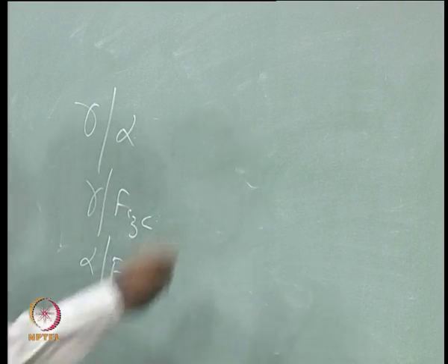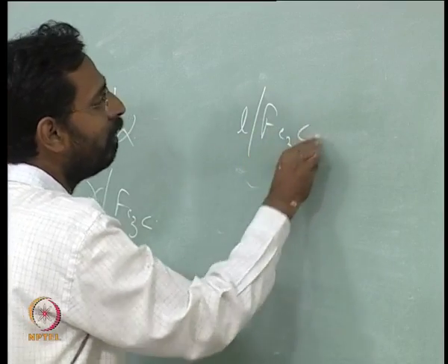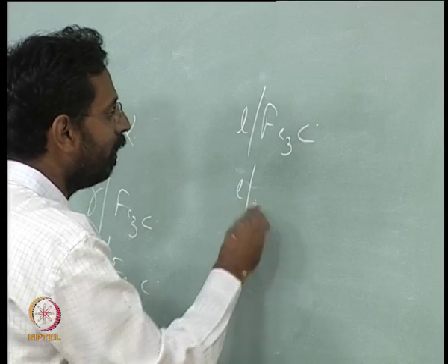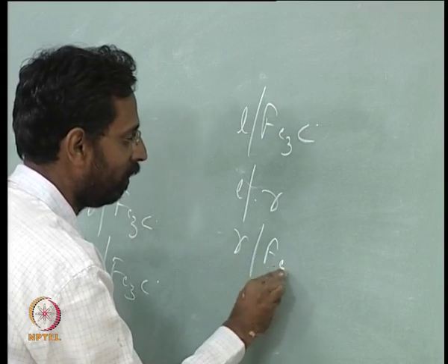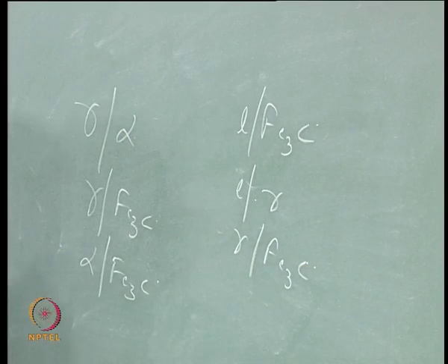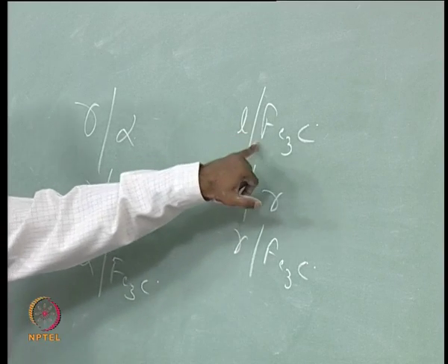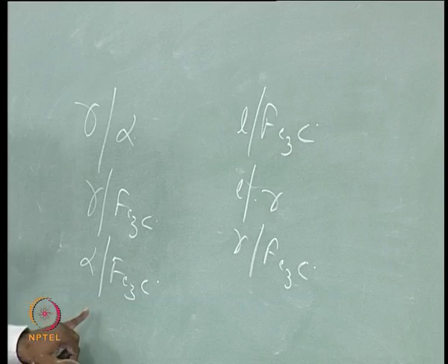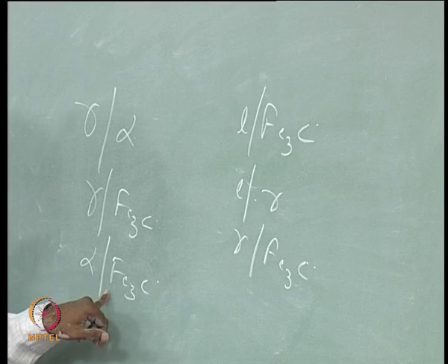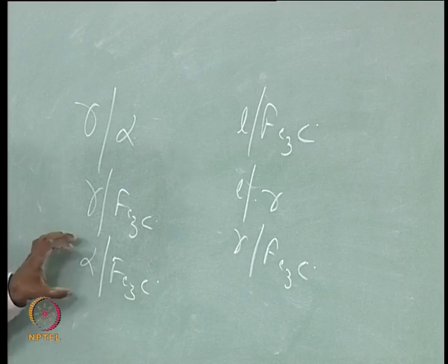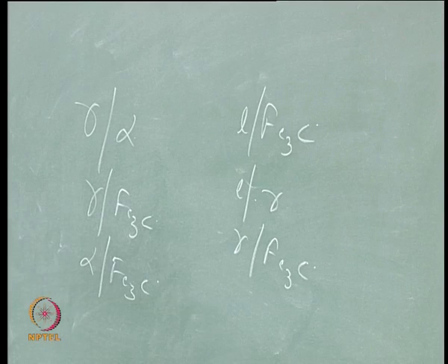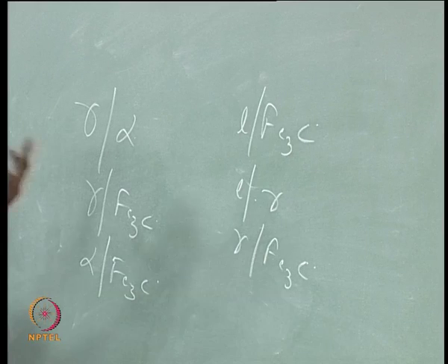In the eutectic case, what I have bothered about is the liquid Fe3C interfacial energy, and then the liquid alpha or gamma interfacial energy, and the gamma Fe3C interfacial energy. These are the three there. So, if you consider that this was lower, and here if you consider this is lower, that is it, as simple as that. It looks at which is the lower interfacial energy, and whichever is lower would happen. And one more thing is, once it nucleates, whether it grows as chunky or not depends on the growth rates. That is what I have just now said.